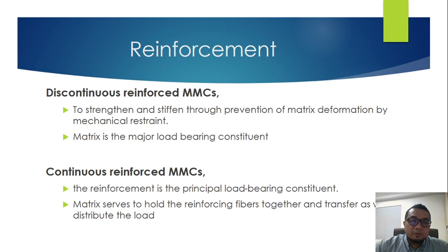So this is the type of reinforcement. Discontinuous reinforced MMC strengthen and stiffen through prevention of matrix deformation by mechanical restraint. The matrix is the major load bearing constituent. I explained the other day the types of reinforcement, either particles or fiber, long fiber, short fiber, discontinuous, continuous. So this one is for continuous and discontinuous reinforced.